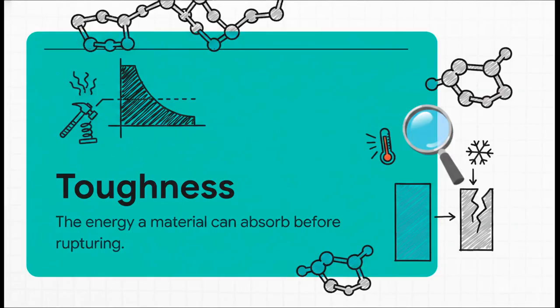Think of polymer molecules like a tangled bowl of spaghetti. If those polymer molecules can quickly disentangle and respond to a sudden, violent mechanical stress, like they do in flexible vinyls or polyethylenes, the material behaves toughly. It absorbs the blow. But in stiff, rigid polymers like polystyrene, those molecular segments are essentially trapped. They can't respond fast enough to that rapid stress, which leads us to our second definition, brittleness.